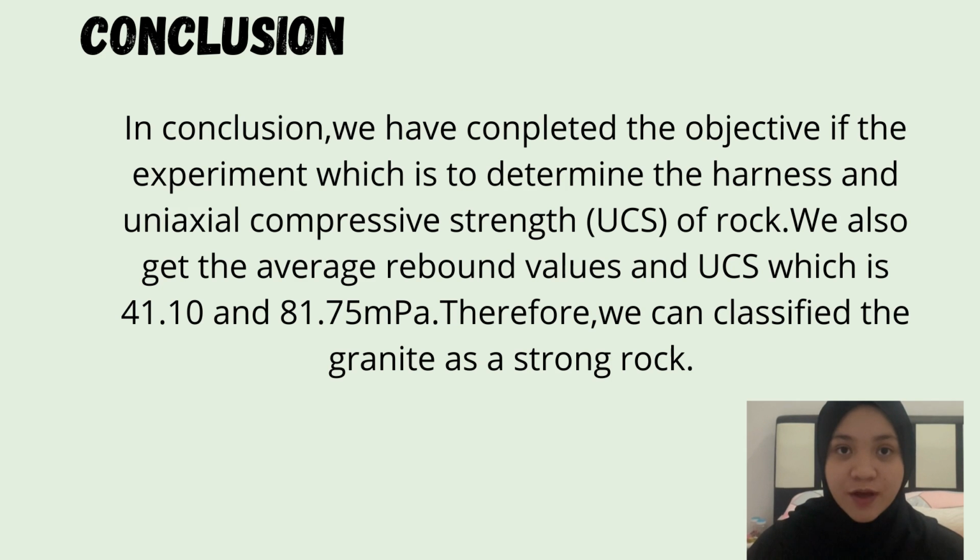In conclusion, we have completed the objective of the experiment, which is to determine the hardness and uniaxial compressive strength (UCS) of rock. We also get the average rebound value and UCS, which are 41.1 and 81.75 MPa. Therefore, we can classify the granite as a strong rock.